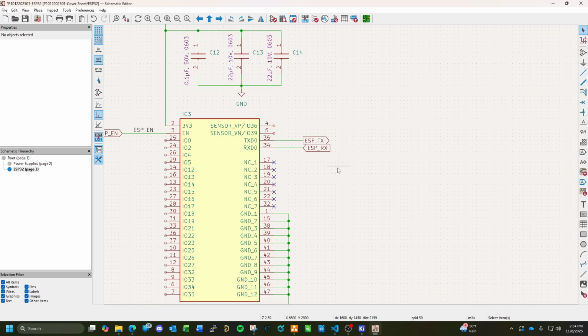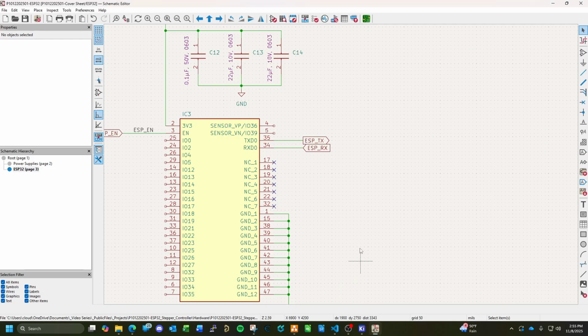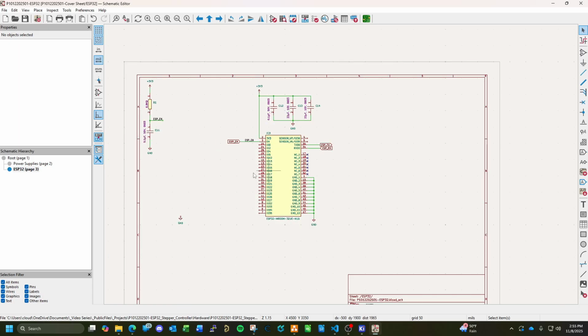All right, because those will be on a separate sheet. Those ports will just connect over there. That's going to be mainly for programming. Now let's figure out some of our plumbing based off of this, as we can start creating ports, because there'll definitely be on different sheets because we're just running out of room on this one sheet to hold everything, and that's fine. This is a perfectly acceptable way to set up schematics.